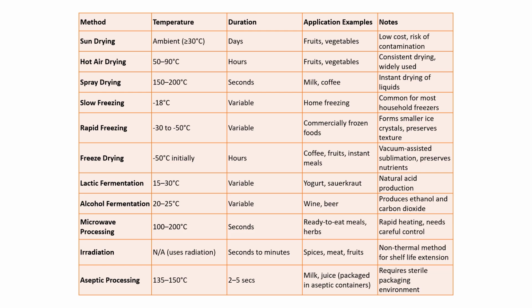Next is aseptic processing, 135 to 150 degrees Celsius, 2 to 5 seconds. Milk or juice packed in aseptic containers. Okay, requires sterile packaging environment.